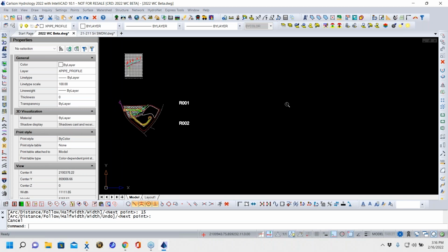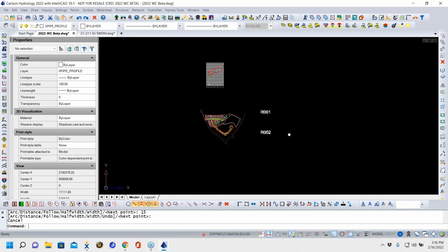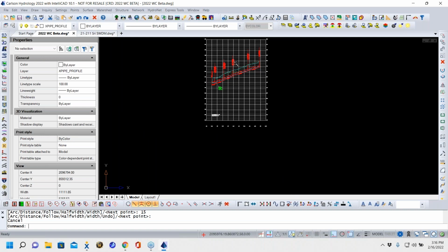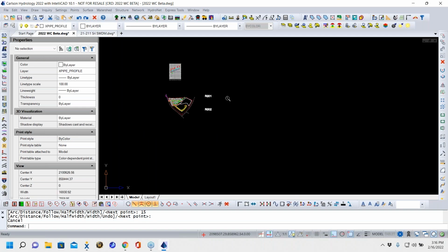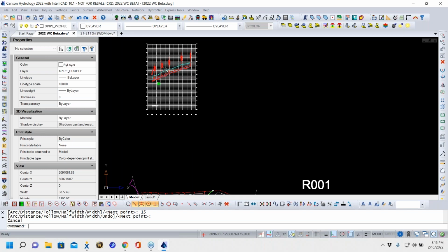Then I'll come down here and draw those pipes on a road vertical. So anytime I make changes, I change the master, and they automatically get changed in my vertical roadway profiles, which sit over here. That way I don't change them there; I change them here in my masters.